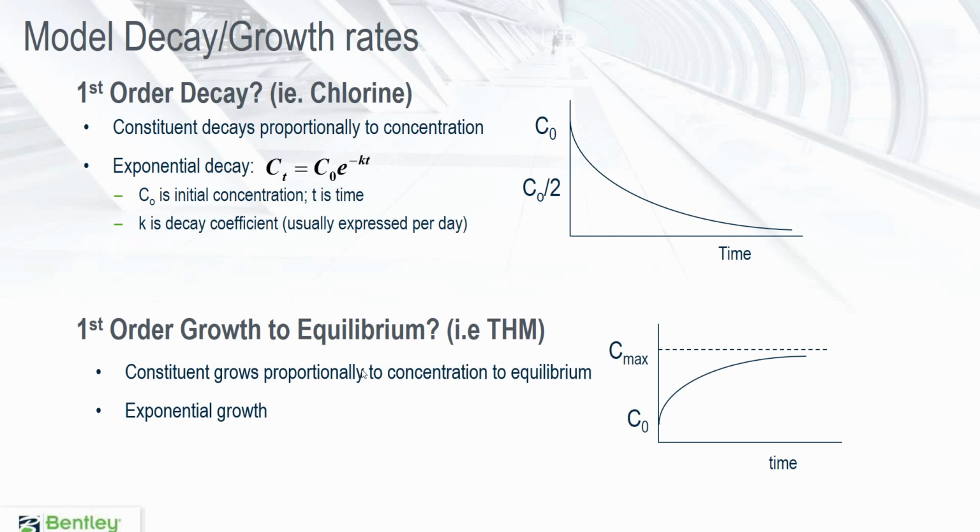So there's a behavior of the constituents, if you will, out in the water distribution system that are all being driven by temperature and pH and the other background constituents and chemicals in the water. So where we're heading is trying to digest that decay rate into something that's predictable, that we've derived from somewhere, and then we can go into the water quality model and say, here's the behavior of that constituent.